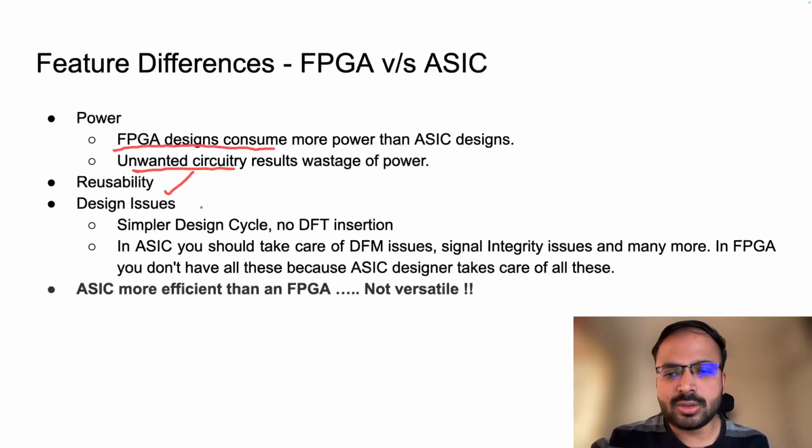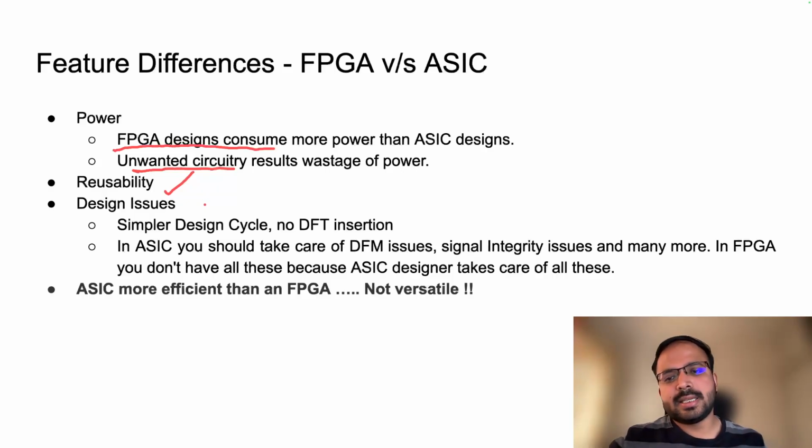What about design issues? The way of designing ASICs and FPGAs is different. The design steps are more in ASICs, so there will be a lot more design issues in ASICs. Therefore, since FPGA has a simpler design cycle, it has fewer design issues.